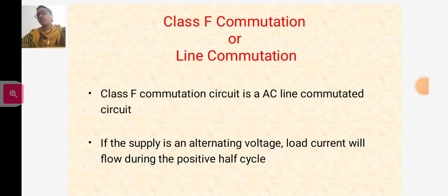In this simple line commutation circuit, during the positive half cycle of input voltage, the thyristor conducts and the source voltage is transferred to the load.